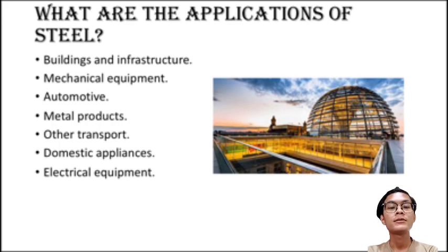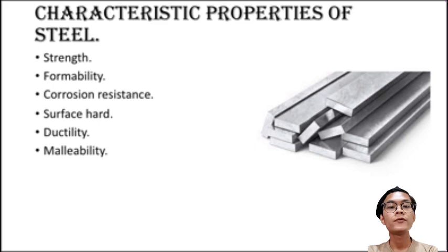Last, steel. Steel is an alloy of iron and carbon in which the carbon content ranges up to 2%. With a higher carbon content, the material is defined as cast iron. It is by far the most widely used material for building the world's infrastructure and industries. It is used to fabricate everything from a sewing needle to an oil tanker. In addition, the tools required to build and manufacture such articles are also made of steel.